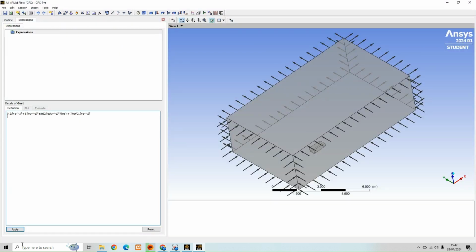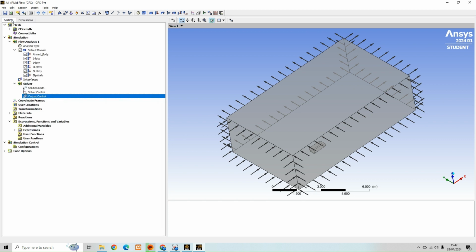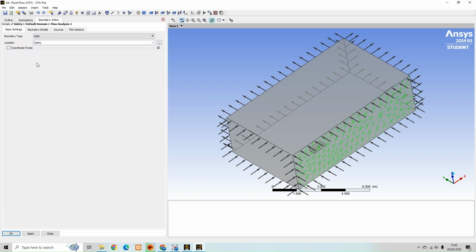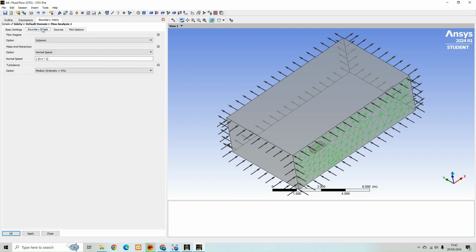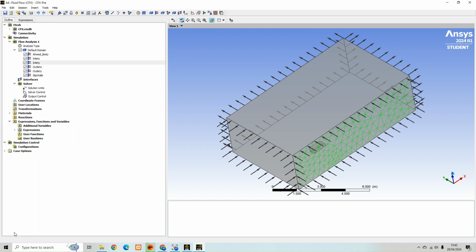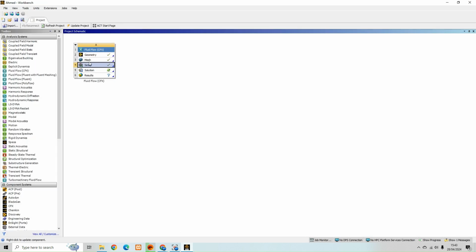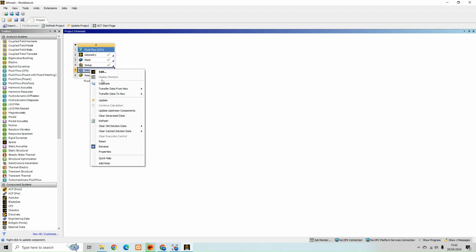So just copy and pasting that into there. Hopefully no issues. Good. And then I'll put that into inlet Y there. When it asks for speed, I just hit the expression and just type gust. Worth saving at this point. Don't think I've missed anything, but if I have, I'll go back, correct, and then update the video appropriately. So just save and open up solution, I suppose.